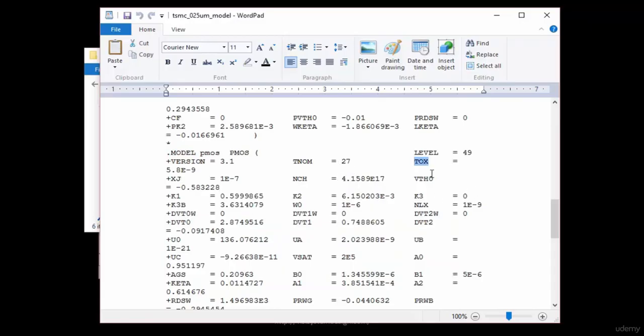So in this file you will see an attribute called NMOS, and all the descriptions related to that particular NMOS, all the parameters related to that particular NMOS. Similarly, you will see a keyword called PMOS inside this model file, and all the technological parameters related to this particular PMOS. Okay, so without wasting any time, let's try to move on and do the SPICE simulation.